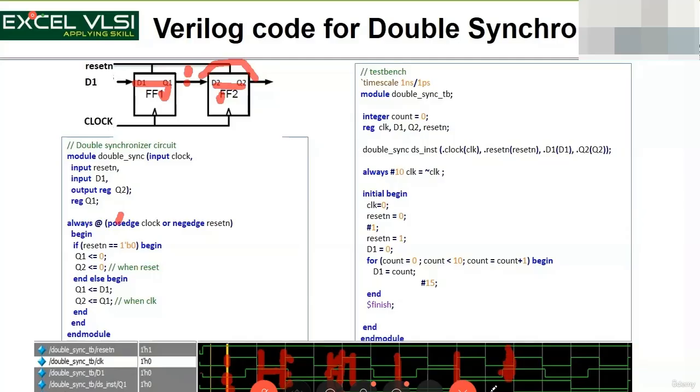Now what I did is dynamic timing analysis. Dynamic timing analysis I am doing because with respect to time, over a period of time, the clock period is, let us say, 10 nanosecond, 100 megahertz clock I am running. Every clock I am checking whether any of the data coming in is not meeting the setup and hold criteria. Okay, so now this is what is called dynamic simulation. And the same when you do it with delays. Now this is done without delays.